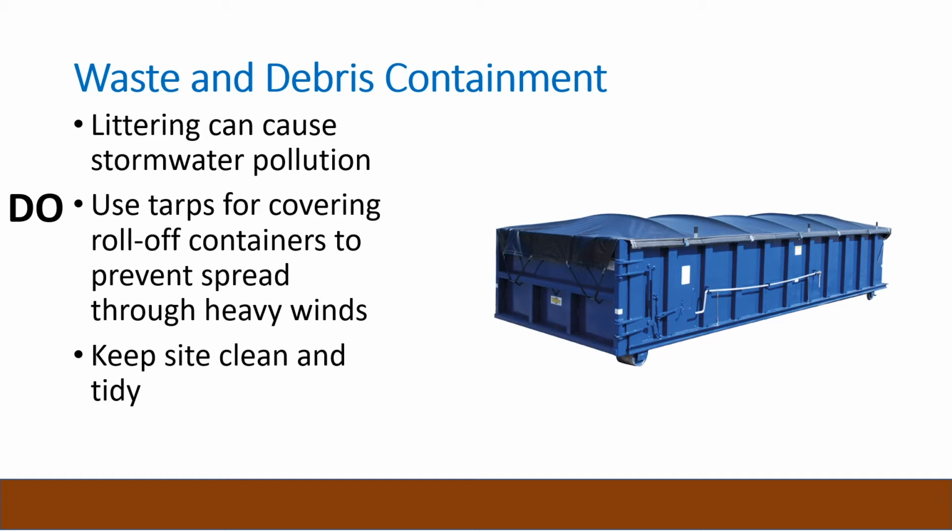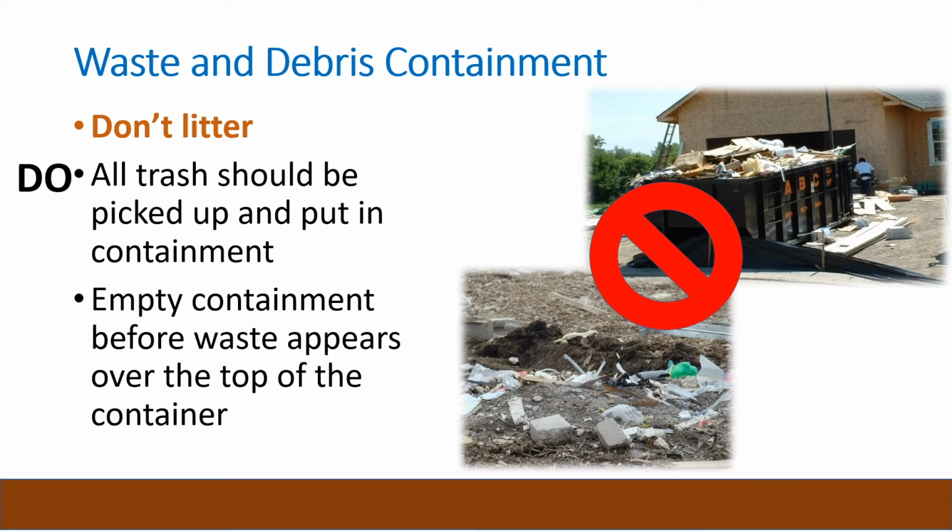Waste, trash, and debris containment. Litter is considered a stormwater pollutant. Use roll-offs to contain waste and cover them with a tarp to keep the waste from blowing out of the container. Don't litter. Pick up all trash and put it in the on-site container. Empty the container before waste appears over the top.